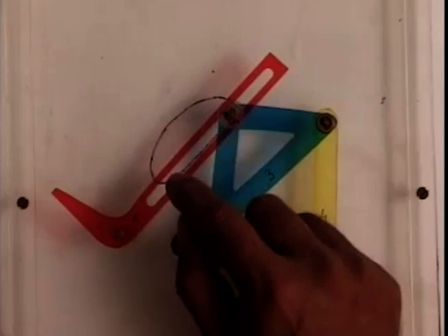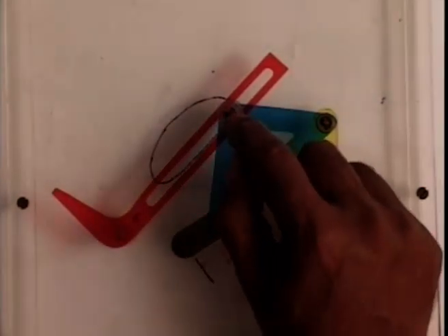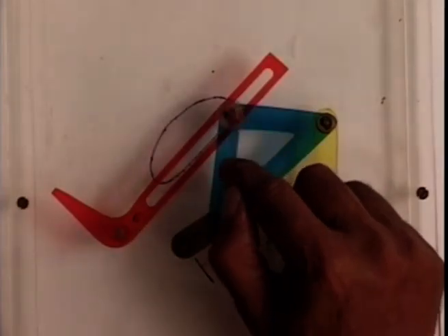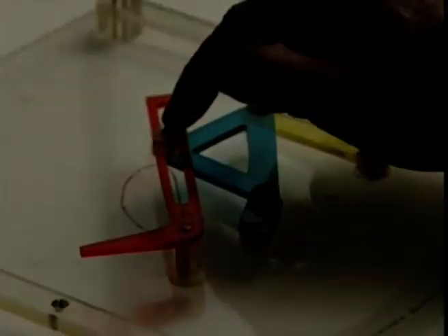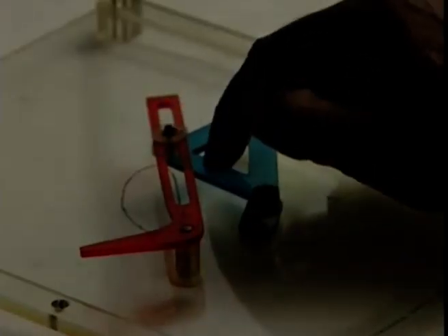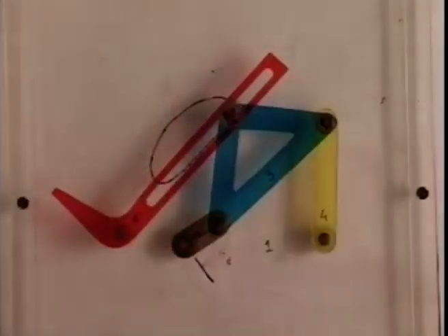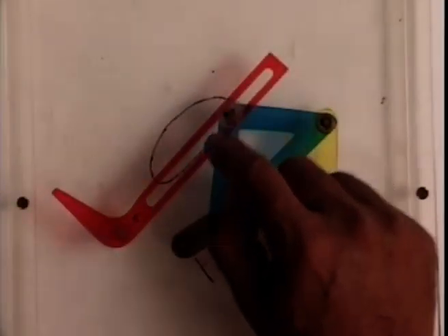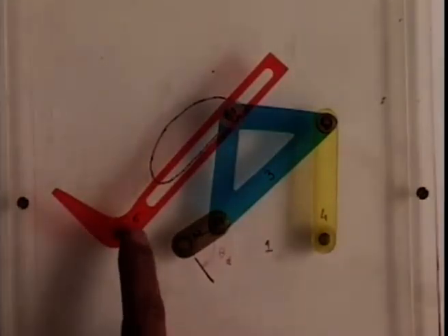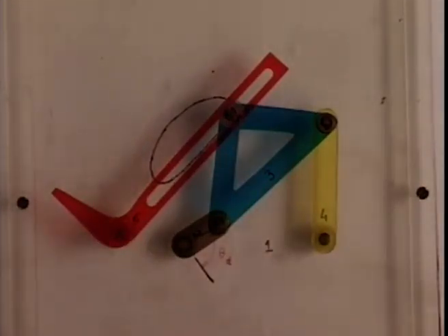This path consists of an approximate straight line portion. So we have a slider prismatic pair here with link 5 and link 4, and there is a revolute pair between link 5 and link 4, and with link 6 there is a prismatic pair in which this link 5 moves. So as long as this coupler point moves along the straight line path, the output link, that is link number 6, does not move,